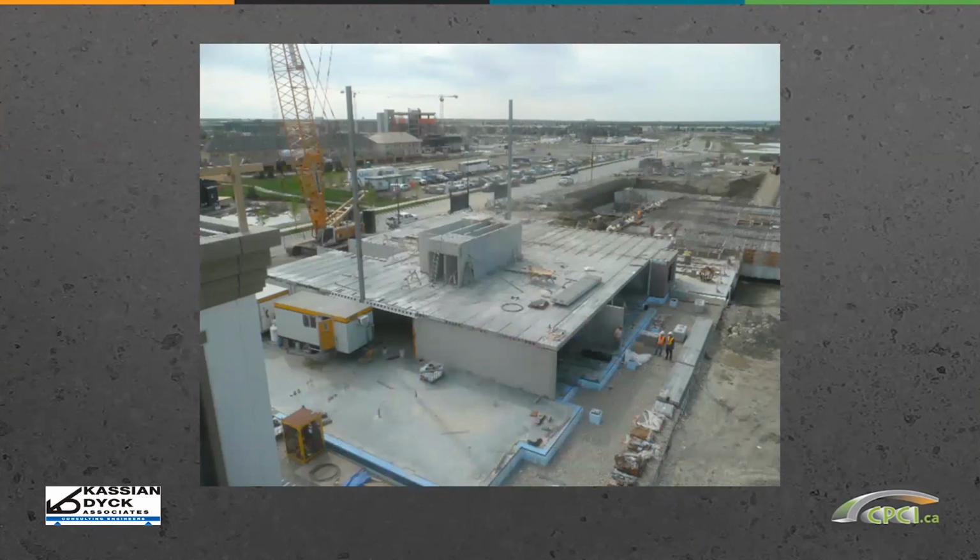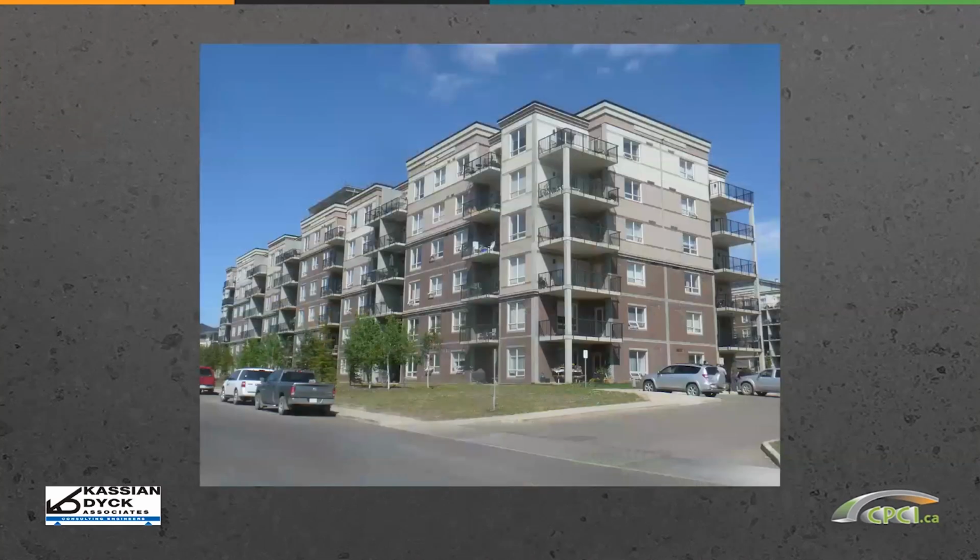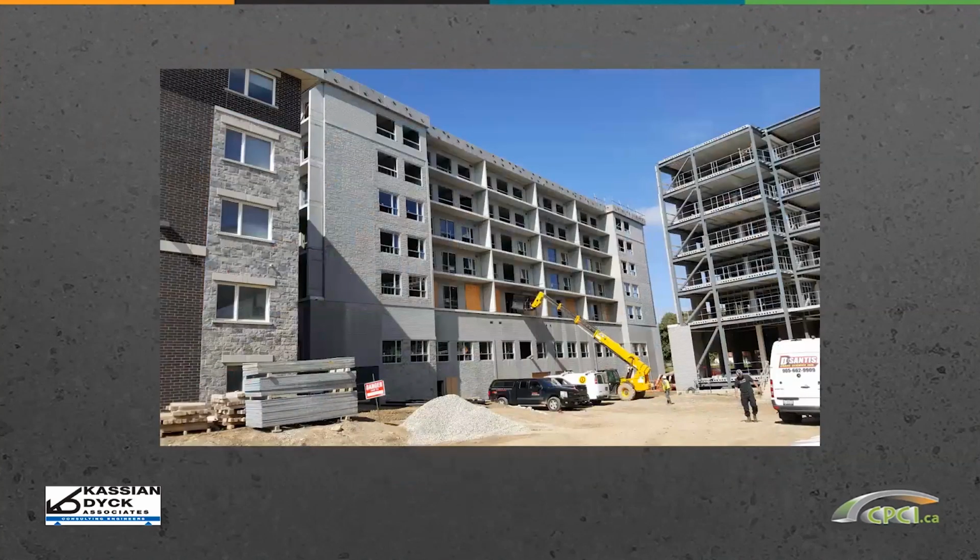Basically, diaphragms are that horizontal floor or roof plate component, which is an important aspect of structural design that is used to transfer the lateral forces to the lateral load resisting system. It's typically used in total precast structures where hollow cores form floor and roof assemblies and are used to transfer loads to the shear walls or cores, and can be used in other types of structures as well.